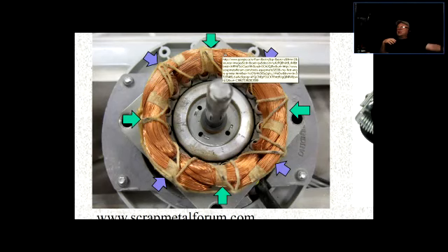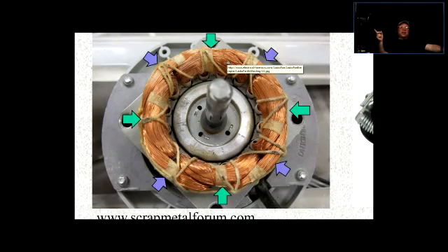It is going to settle down, and those main windings are going to hit the single phase at the right time, and the motion is just going to be supported by that. If you stop the motor, then the centrifugal switch is going to close, make a contact again, and then you're ready to start that again.